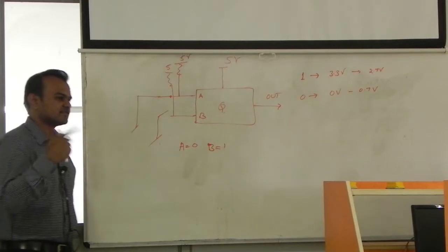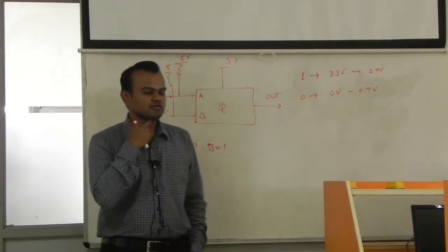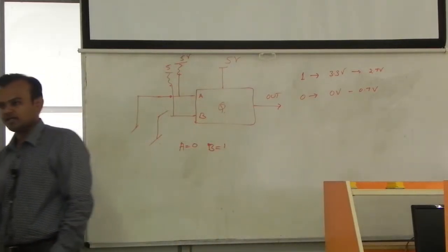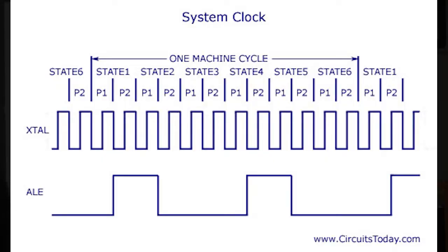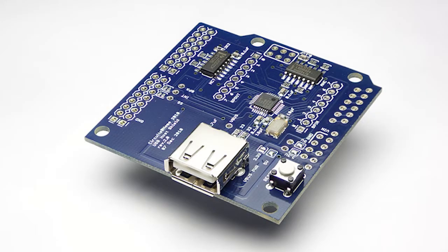From a smaller source, it is able to generate a large clock. So even with a small source like 12 megahertz, we can generate clocks up to 320 megahertz in this particular case. For example, for USB specifications, whatever USB devices are there, a particular frequency of 48 megahertz is required for internal working.